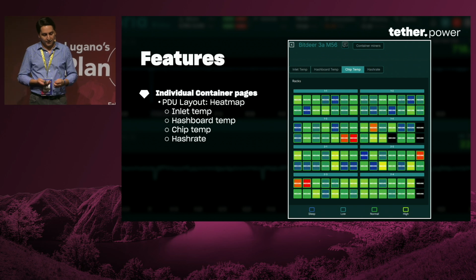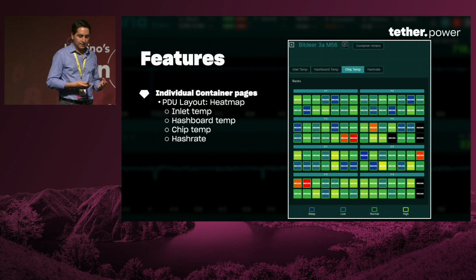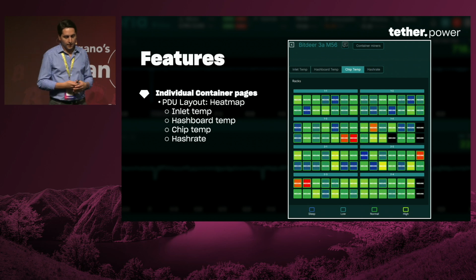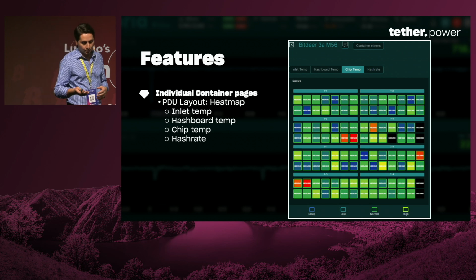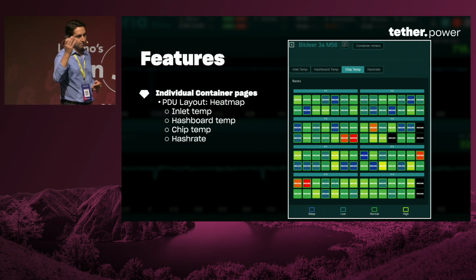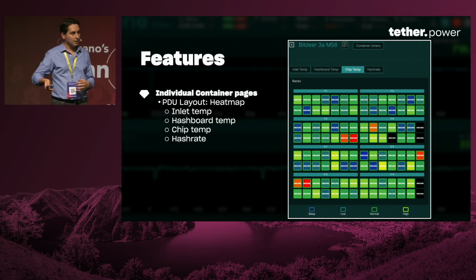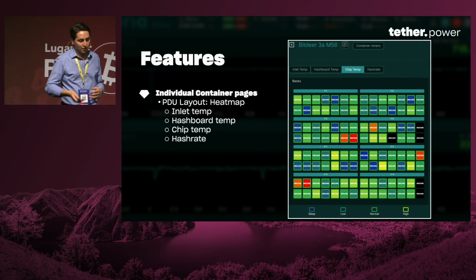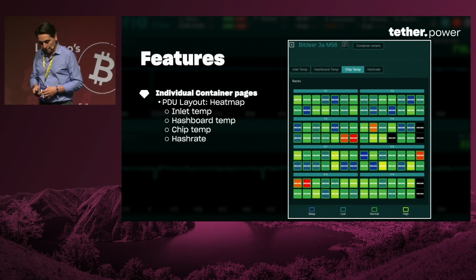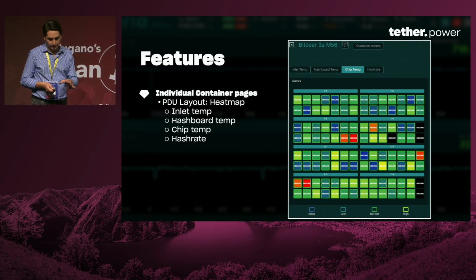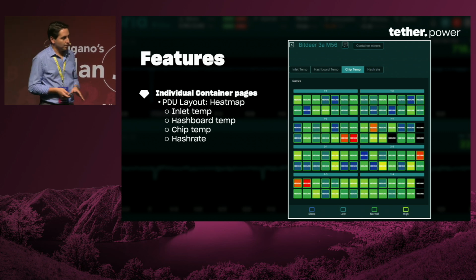Or another application, if you don't want to automate that, is when you're close to the temperature limits, you look at the hash rate temperature or chip temperature and say, OK, those 5 or 6 miners are the hottest ones. I'm going to turn those down, turn them off, or just lower their consumption. And therefore, again, making sure that they don't actually get damaged because of high temperatures. And again, these things are all things that can be automated.